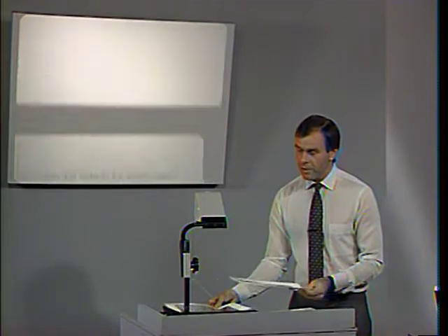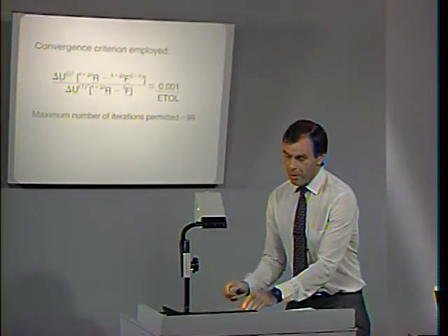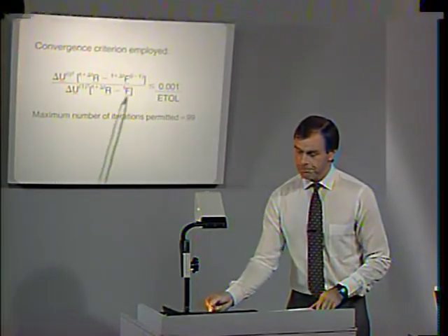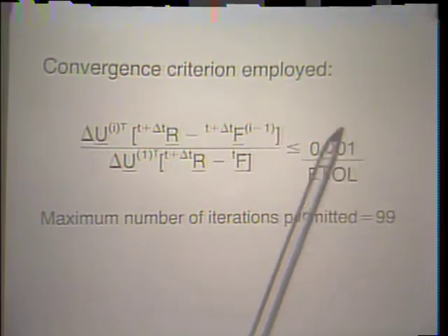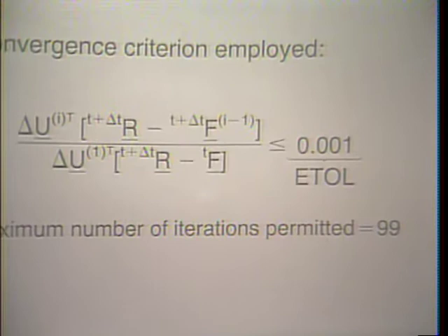The convergence criteria employed for this problem are shown here. Notice etol is given here as 1/1000th, the default in the ADINA program. We used a maximum number of iterations that were permitted, which is very large in this particular case.